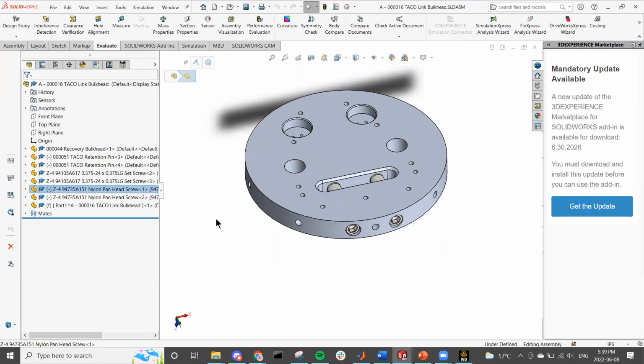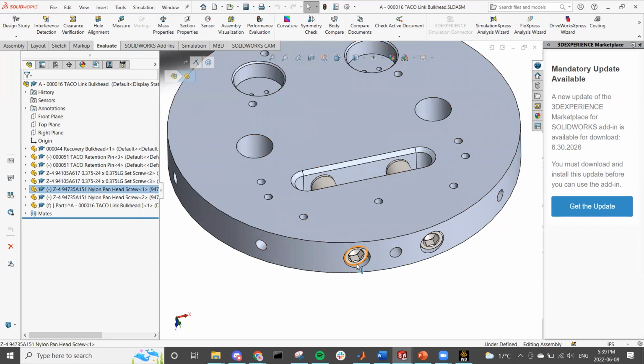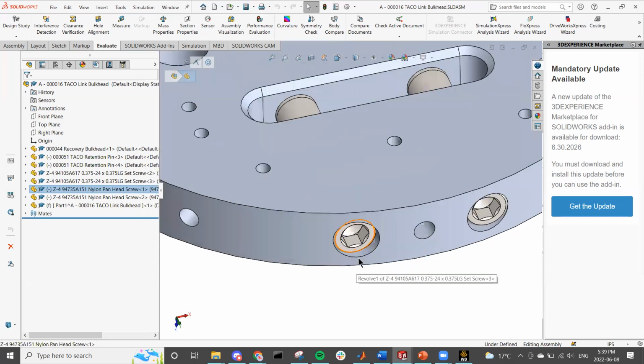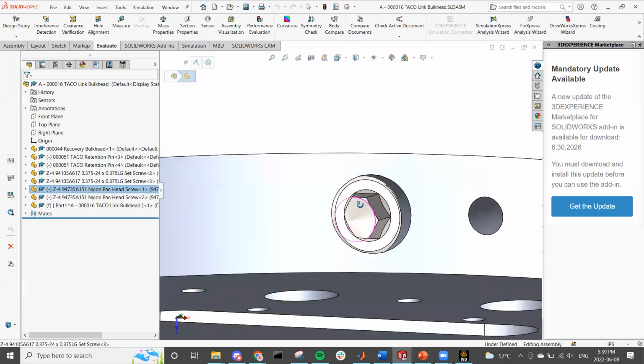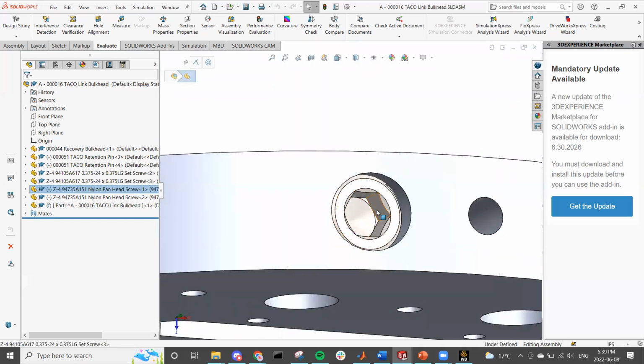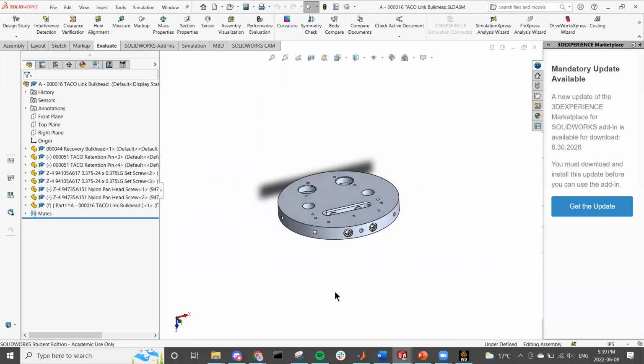In some cases, you will have fasteners that take a lot of load. For example, the ones that mount the fins to the fin cage have preload and are taking a lot of load, so we do model those fasteners. But if you want to model fasteners, you should delete the threads and simplify the head. In this case, I would just model this as a solid cylinder and delete all of those faces if you can.